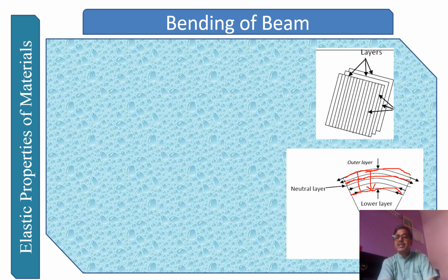You can look at this layer. See this layer properly. In this layer there is neither elongation nor contraction. Again, I am representing this with the yellow line. This will be called the neutral axis. So what is the neutral axis? If you bend the scale, in between there is a layer where there is neither extension or elongation nor contraction, and that axis is called the neutral axis.